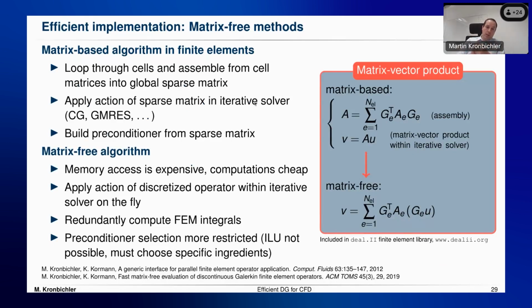And the idea of a matrix-free solver, I mean, here I just had these gather operators where I just say how I would assemble a global matrix A and eventually apply it. And when you do matrix-free, you just run the element loop in the iterative solver. So this is, from a software perspective, not so interesting. The reason why we do it is that when we apply the discretized operator from the finite element integrals, we redundantly compute those integrals. You could then argue if it's more work to do than building a matrix.